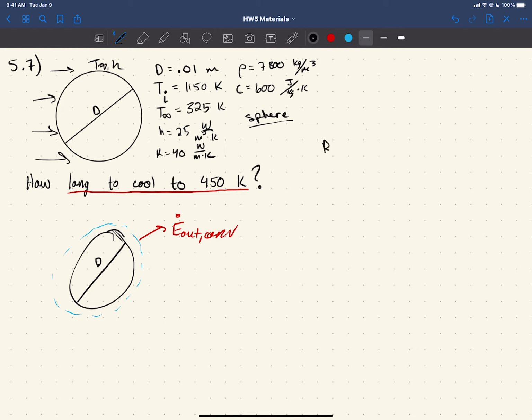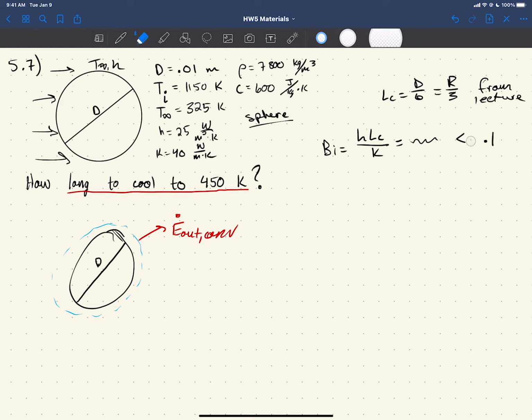So we have to calculate our Biot number. Our Biot number is h L_c over k. So we have to get our L_c. In this case, I'm just going to say L_c is D over 6, or R over 3, from lecture. You should be pretty good at that by now after watching me do all those. So you plug the numbers in, and the Biot number here, I forget what it is, but it's less than 0.1. I don't really need that much less, but it's definitely less than 0.1.